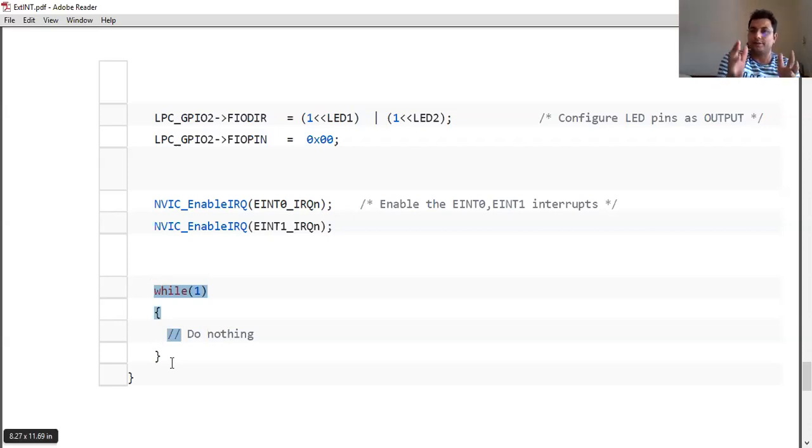And in the whole program, as you can see, we are not continuously checking any external interrupt pin. We're not checking it. NVIC, the nested vector interrupt controller, would acknowledge our interrupt. Because already you have enabled 2 interrupts, it could acknowledge only 2 interrupts. It would not acknowledge other interrupts, even if you were to connect your pins. Until and unless you configure those pins and enable those interrupts, your interrupt controller would not acknowledge those interrupts. Once you have done it, everything is done.